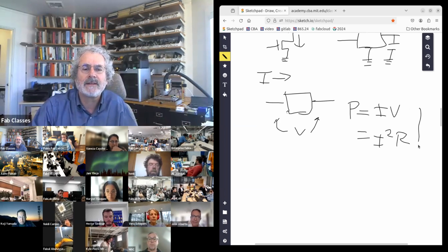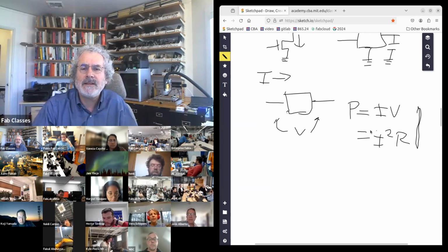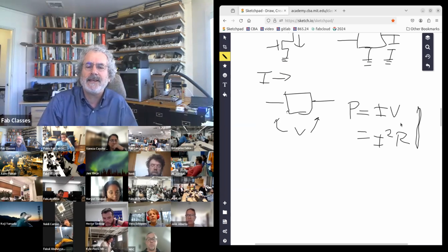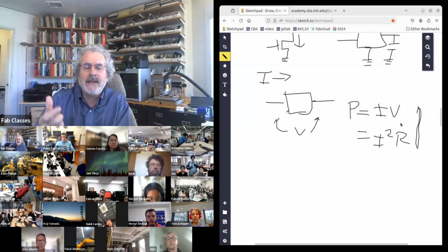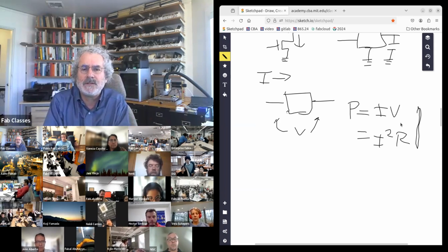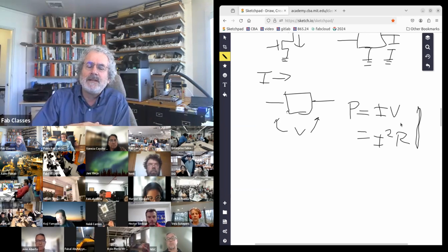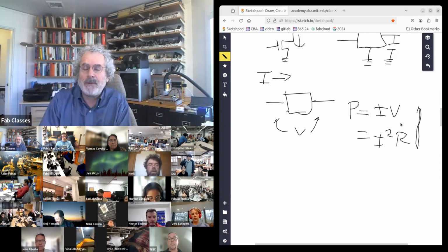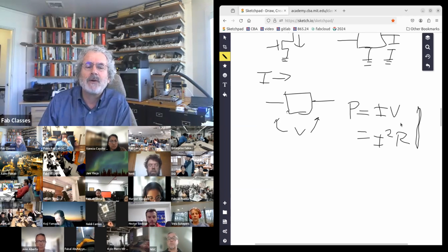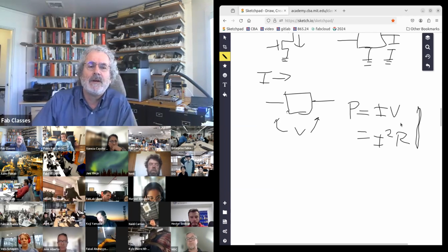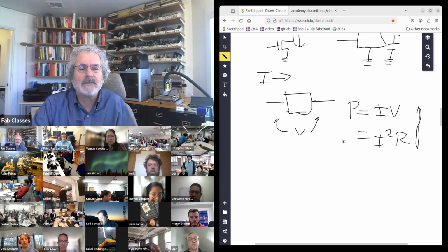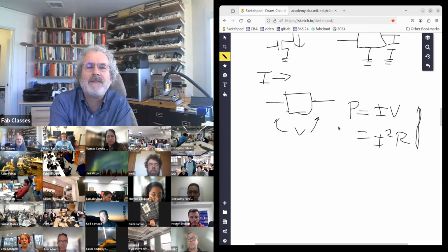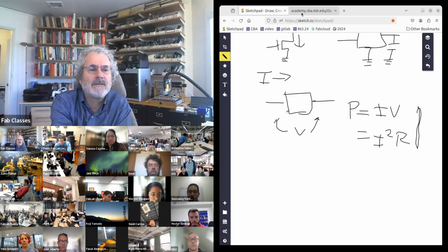So this can sound abstract, but as you run into this, you can need to put heat sinks on components to help them cool. You can need to change component families to reduce dissipation. You can need to move to bigger batteries or bigger power supplies. And so this might control how long a sensor lasts in the wild. And so power is going to be a very important thing to be aware of.